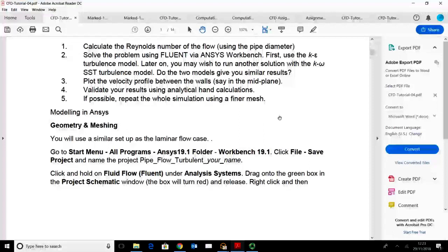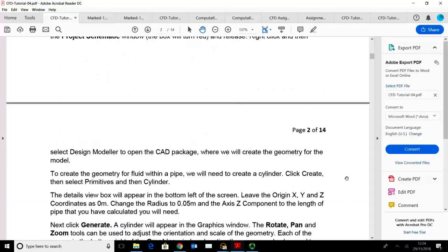Then, rather than doing a full cylindrical fluid element for the simulation, you get a quarter of a pipe. You simulate the quarter of a pipe. When you do this, you define two symmetry planes because you assume your x and y velocities to be symmetric or axisymmetric in this case. And all the changes will take place along the z-axis or the axial direction.